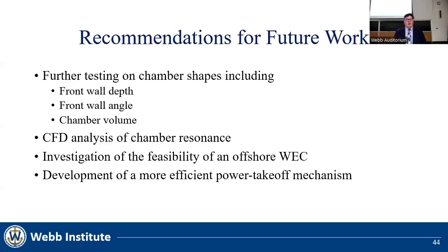A future thesis could design a chamber to isolate each of these variables to determine their effect on overall system performance. The second recommendation is to perform a CFD analysis of chamber resonance, which is currently done by the major companies designing oscillating water columns. The third recommendation is to investigate the feasibility of an offshore wave energy converter, which might be better suited for testing in the Robinson Model Basin. Finally, the fourth recommendation is to develop a more efficient power takeoff mechanism that does not limit the system in the same way that the DC generator does.